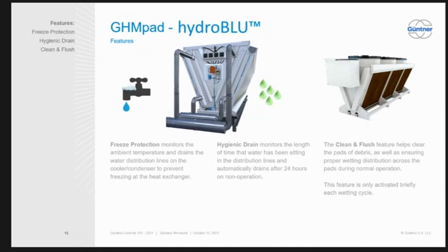When I hear these things, I go back to the factory and we work on it to fix it. There was a problem where the drain was reverse acting instead of direct acting, and it was causing a whole lot of problems, where it was draining when it shouldn't. But I think we've worked through that now, and hopefully you don't see that as much.